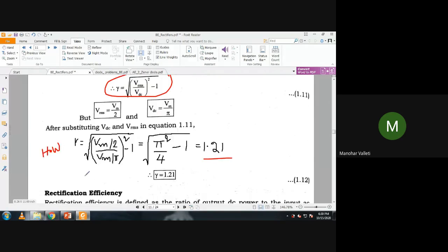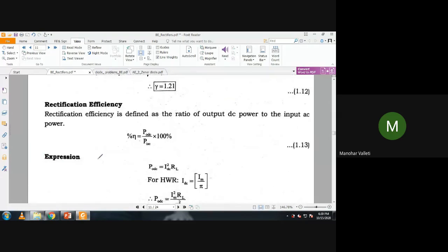The same way, rectifier efficiency is the ratio of the DC output power at the output of the rectifier to the AC input power. It means how much AC is converted to DC. Let us say if you give 100 volts AC, you expect 100 volts DC to come, which means the conversion efficiency is 100%, without loss of any energy. But that is ideal, right? You won't get it because of practical conditions.